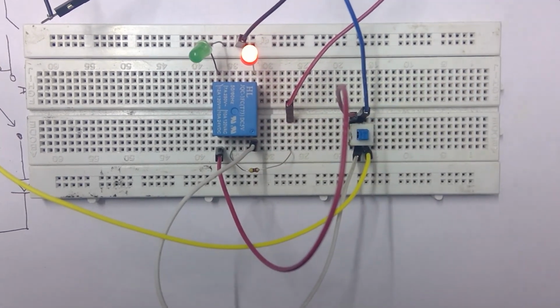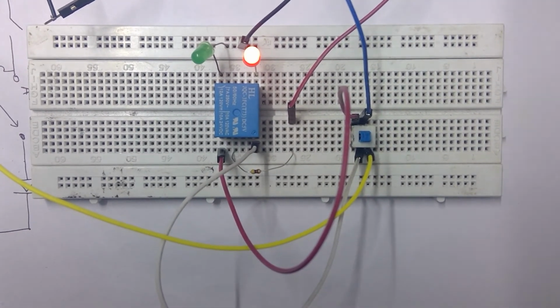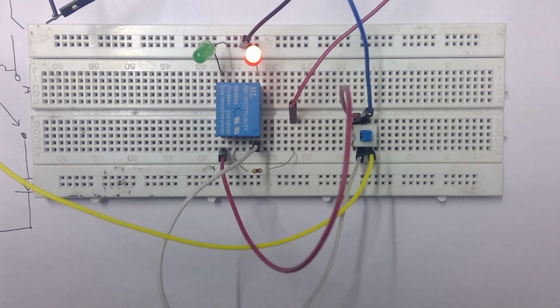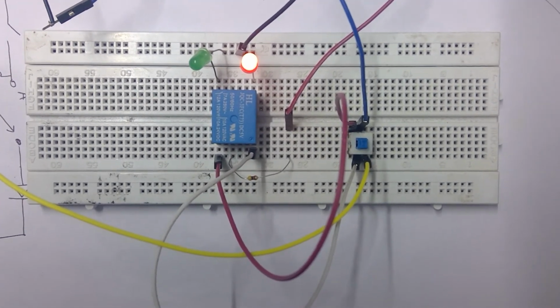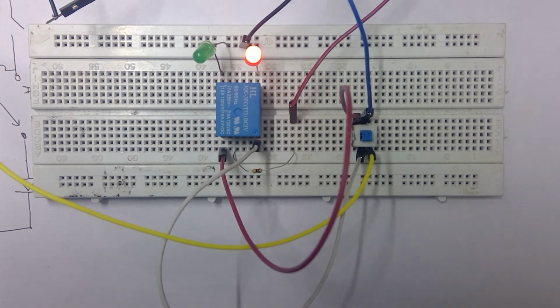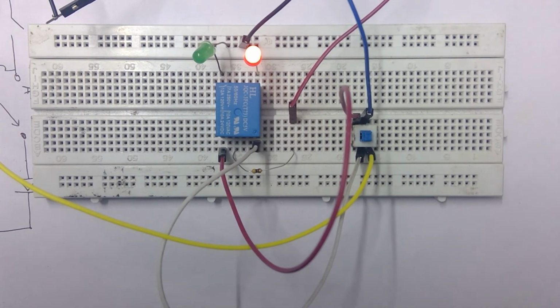So this was a small practical example of how relays can be used to power stuff. The most common example for this is if you're using an autonomous robot, or if you want to do anything with a microcontroller which has a 5-volt output and you want to run motors for a toy car or anything. That is where relays come into play. Practical applications may include pumps, or any other electronic instrument which need to be powered on at a specific point of time.